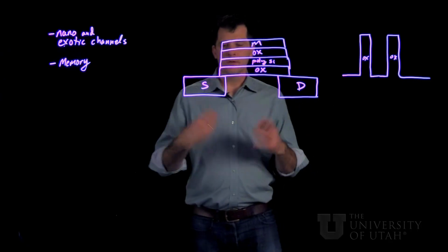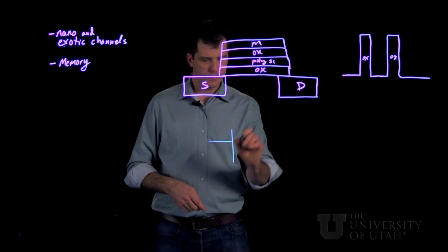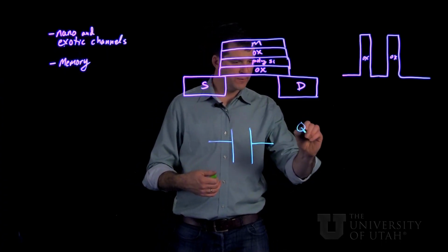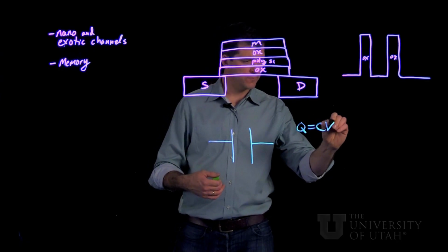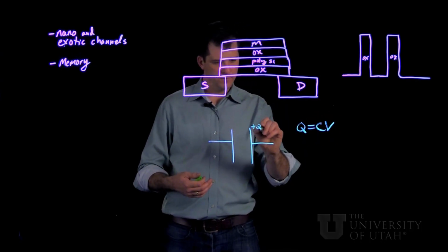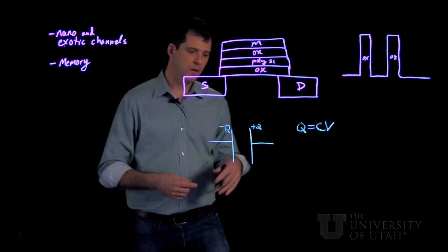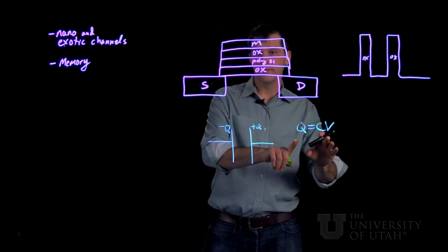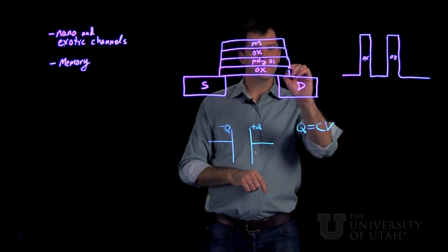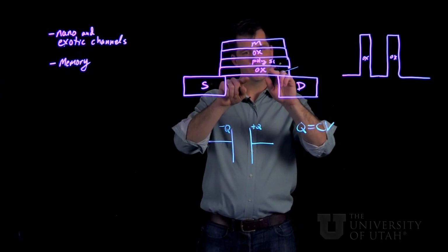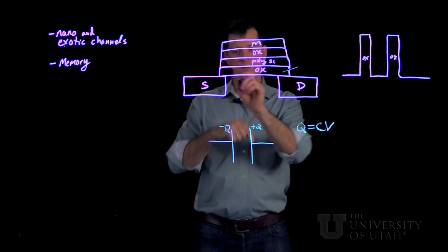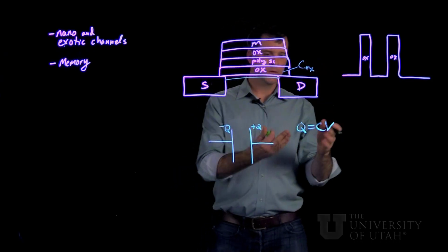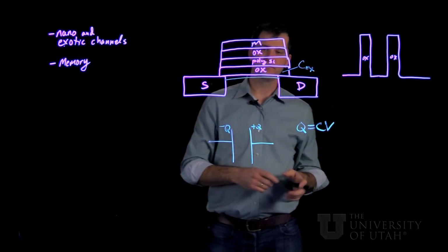Well, if we go back to our definitions on a parallel plate capacitor, we have our relation Q equals capacitance times voltage. The charge plus Q minus Q on this capacitor are directly proportional to the voltage. And if you have a fixed capacitance here, now this is going to be the capacitance between this oxide and the channel, charge and voltage are really the same thing.